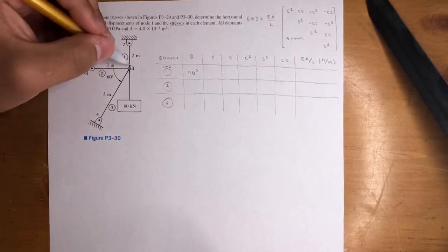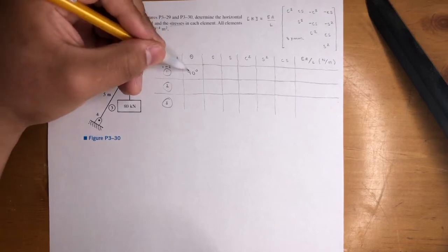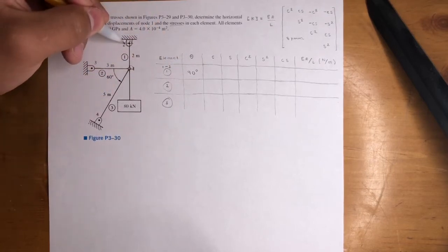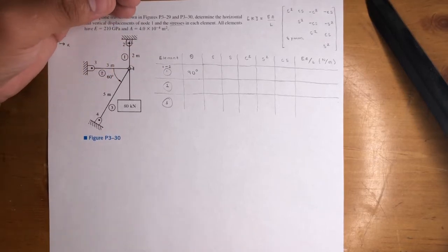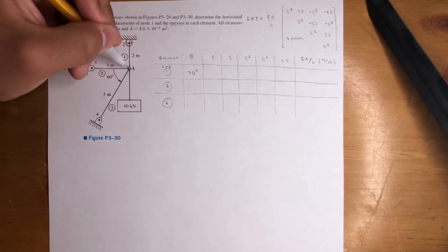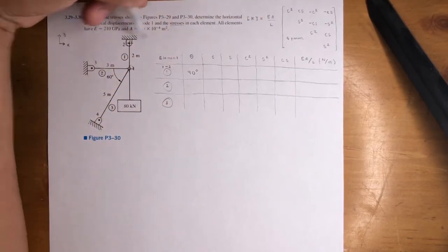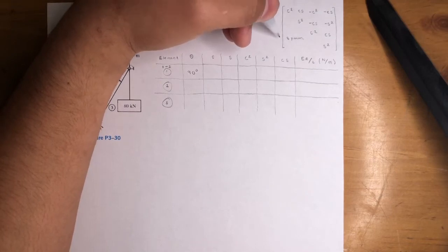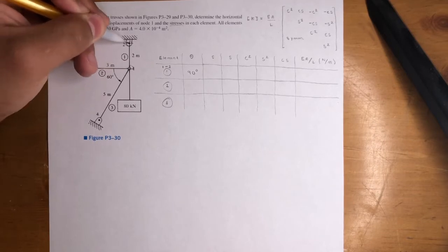If you were to go from 2 to 1, you would have used this as your origin, left and right, up and down, right? It would have been 180 plus another 90, which is 270. So it would have been 270, and your element would have been from 2 to 1, not 1 to 2. So that's kind of how you figure it out. For me, I like to just always use the smallest node. I don't know, for some reason it's just easier when you're doing the matrix. This would be U1, V1, U2, V2, as opposed to the other way, U2, V2, U1, V1. It's just more confusing, at least for me. But I like to stick to the smallest node and go to the bigger node.